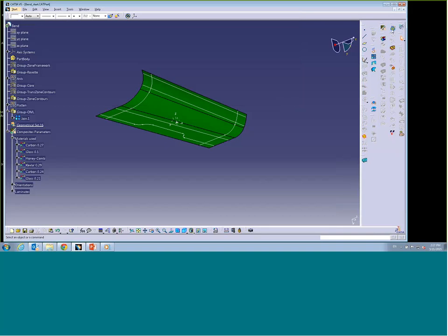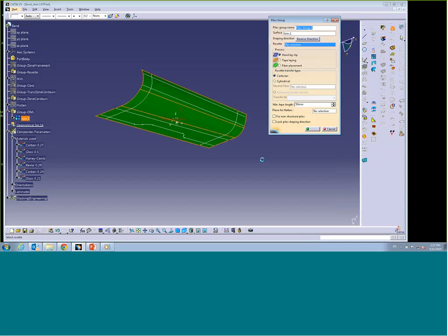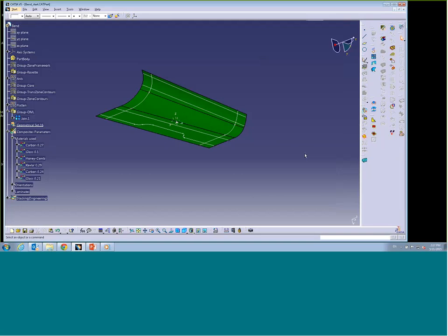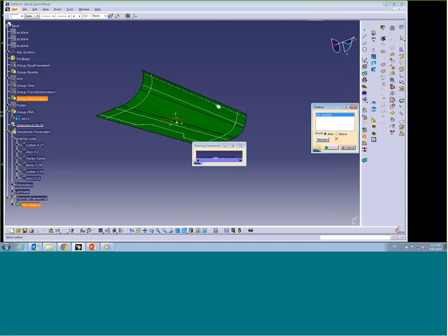With manual ply creation, let me create just a couple plies. So I'm starting with the ply group name, surface, that's my OML, draping direction. As you can see this red arrow, this is how the stack will grow from the OML. Am I okay with this one? Fine enough. And rosette defines the orientation of the ply. The X direction is 0 direction in the ply. Okay, and I can start creating the plies. So let's say I want to start by creating, you see it creates stacking engineering here. I want to put a ply as a ply group, and I want to create a bunch of short plies at the leading edge of this sort of surface.